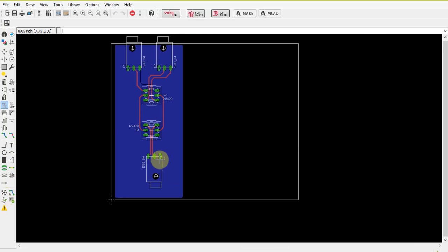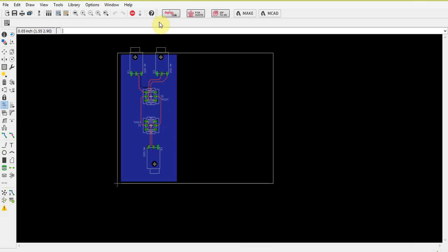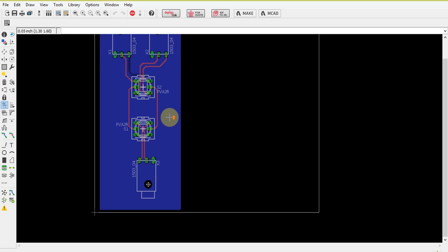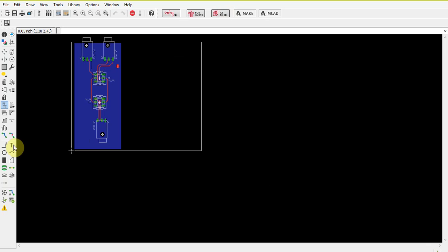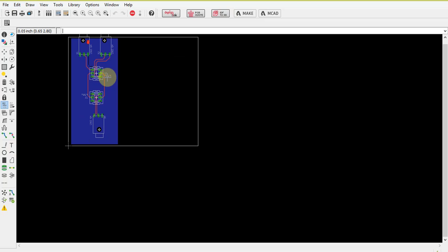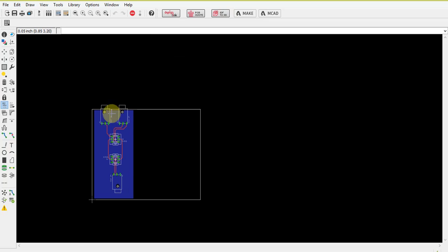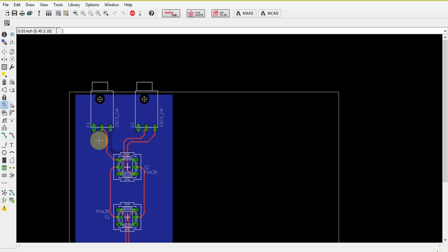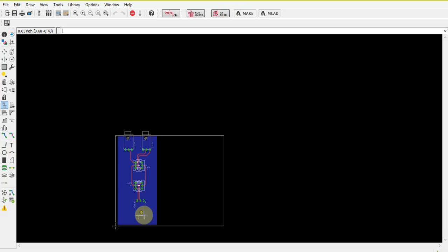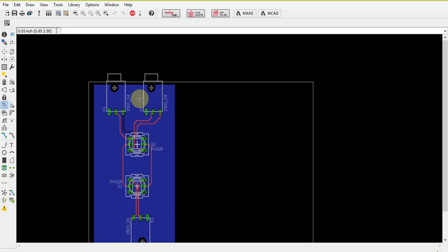So you have this. Of course we can always optimize, make this smaller, make this more compact, move all the components together, but this is just to show you how you go from identifying a simple problem, creating a very simple solution for that, and then doing a final circuit implementation. Of course this is still not completed because I need to figure out mechanical stuff like I said, spacing between components and so on. Probably I'll have to move these closer inboard, and this one probably a little bit further away, and I'll move switches together and so on.